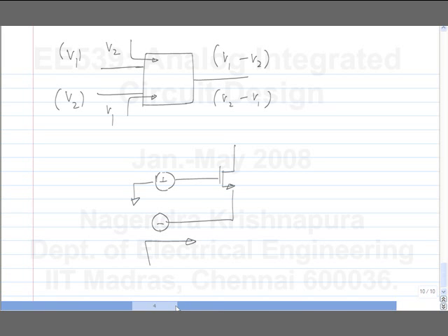Actually, this circuit can be used. Before, in early days, this kind of circuit was used in feedback stuff. But it's not a great circuit because you can't use it universally. You have to know what you are connecting to the gate and what you are connecting to the source. Whereas, for instance, our op-amp model is such that you can take it to any circuit and use it. Because there, in an op-amp, you do know that the two inputs are symmetrical. So this has a very low input impedance looking into one of the inputs.